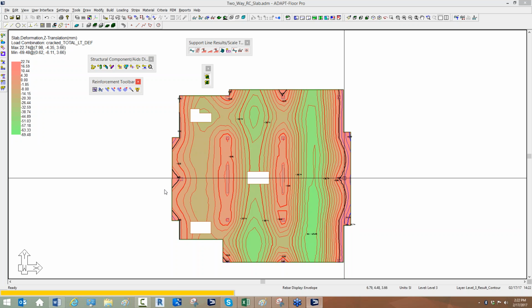Aaron, the skip patterns do only apply to the specific floor. So they would apply only to the floor that they are assigned to within single level mode. They do not apply to columns. We covered column live load reduction in the webinar last week. So if you'd like, Aaron, I can answer offline how you apply live load reduction to columns. I believe we have a video also that covers that topic. But what we talked about today only applies to floors.